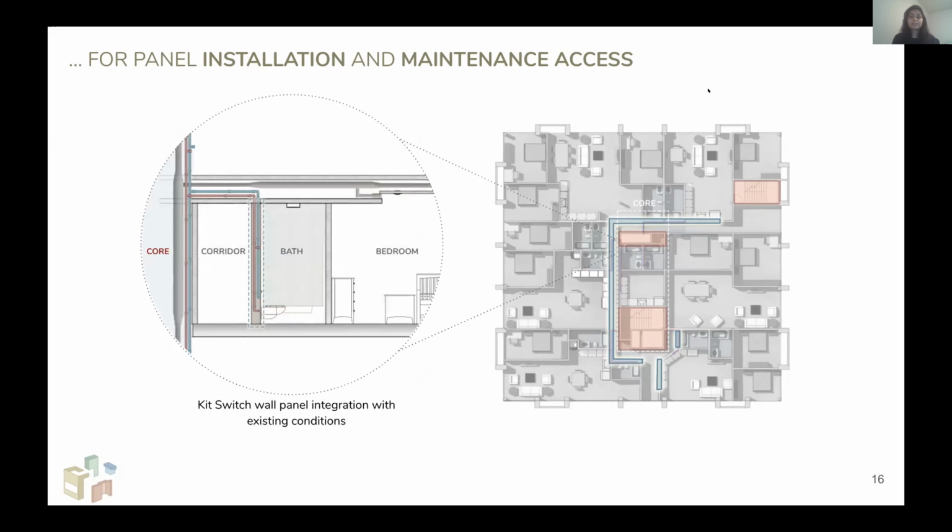And given the higher slab-to-slab height in commercial and office buildings, the MEP distribution would run in ceilings and through the corridor, which then connects to our electrical and plumbing integrated wall system. This makes it easier to pump hot and cold water from the existing core and down to respective floors and through the ceiling.